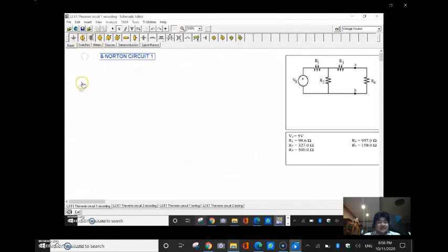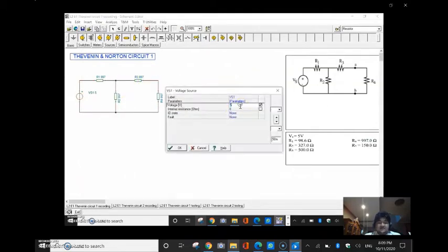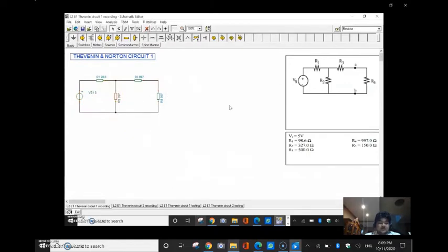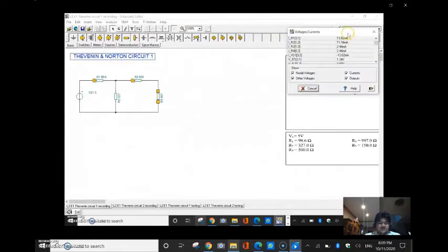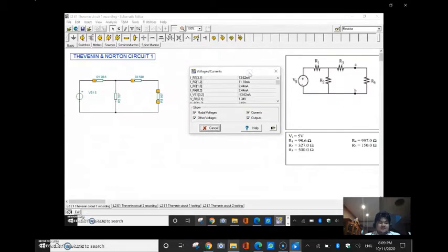Today we will be conducting an experiment regarding Thevenin and Norton circuit. We will be testing the Thevenin theory for simplified circuit using simple circuits with resistors and a DC power source. For the first circuit, we have the schematics and the values for the four resistors on the right side. We have R1 98.6 ohm, R2 327 ohm, R3 500 ohm, and R4 997 ohm with a Vs of 5 volts. We will run the DC analysis with table of DC results.